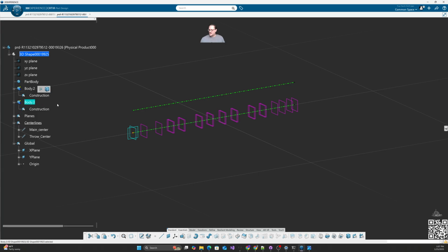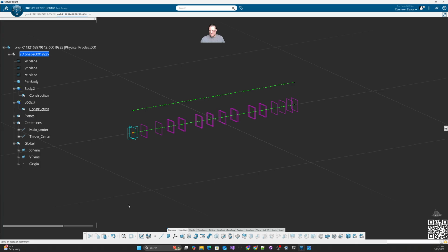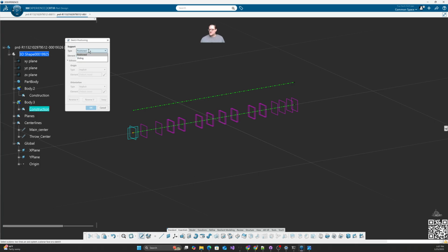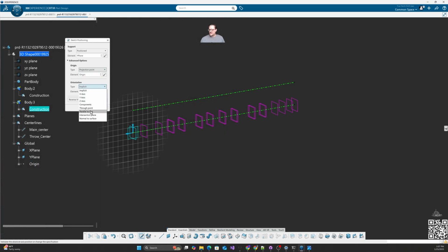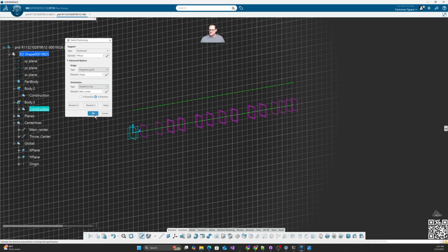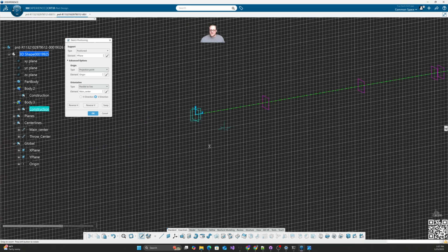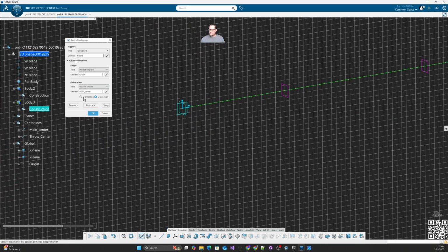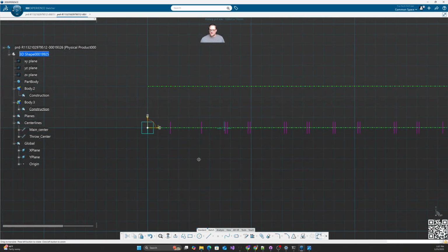So as I said earlier, I am going to copy and paste one of these bodies. I already have one here, so let's define a work object on the construction, create our sketch. So we want a position sketch. We're going to sketch on this plane. My projection point, I'm going to use my origin and parallel to line. So we're going to say parallel to this line. Let's have a look at my V and H. Are they back to front? It looks like they are back to front. So let's say H. Let's reverse the V. Okay. So that's got the right orientation that I would like.